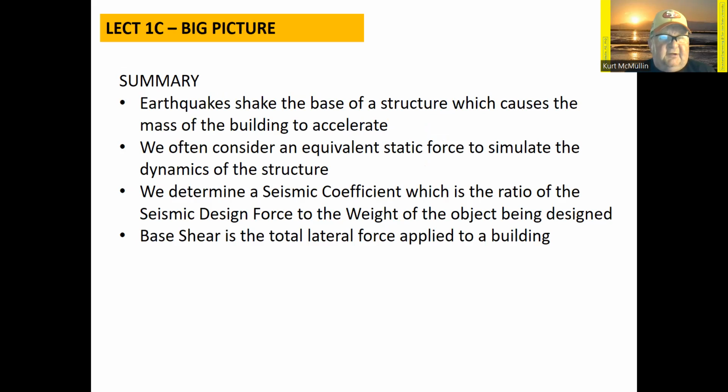Earthquakes shake the base of the structure, which causes the mass of the building to accelerate. It's a complex, three-dimensional dynamic situation. We're going to replace it with what we'll consider an equivalent static force so that it's something that we can work with and have quantifiable values to determine. Seismic coefficient is the ratio of the seismic design force to the weight of the object that's being designed. And base shear is the total lateral force applied to a building during an earthquake.